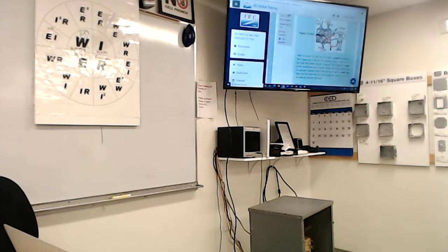Up to 4, more than 4, yeah. More than 4, you would add a quarter volume allowance. That's new in this code. But we ain't got more than 4 in this box.